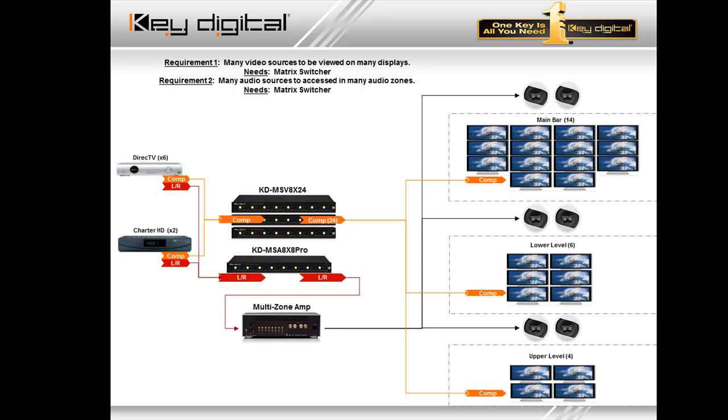Pro audio matrix. And what's nice about this is the MSA 8x8 Pro features the volume control, for example, the EQ, the audio control of the muting, for example, per output. So really your amplifier, if you'd like to somewhat streamline the feature set of that amplifier, not having to pay the extra bucks to buy the amplifier with the volume control, etc., it's all built into our MSA 8x8 Pro. So it's going to go in as left and right, line level audio, and of course leave that amplifier third party. At this point, Key Digital does not offer an amplifier, leaving that amplifier as speaker level audio.